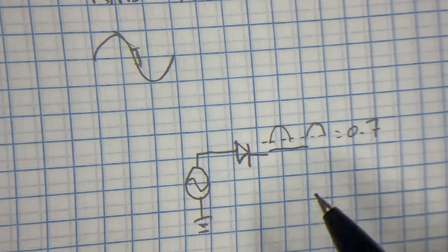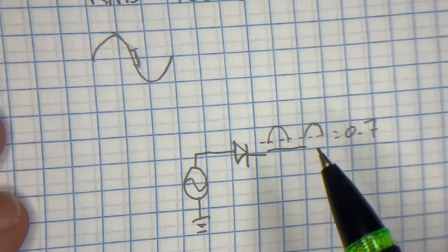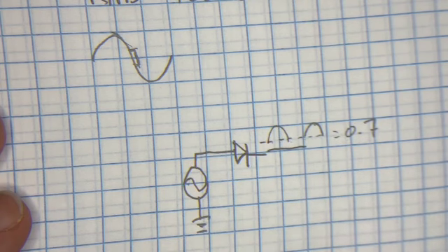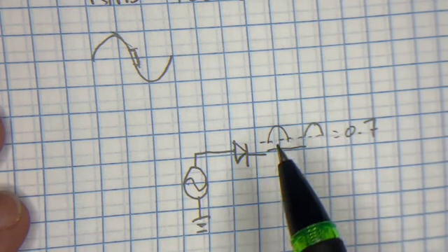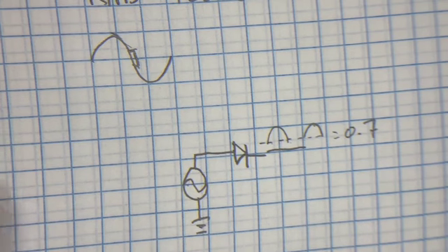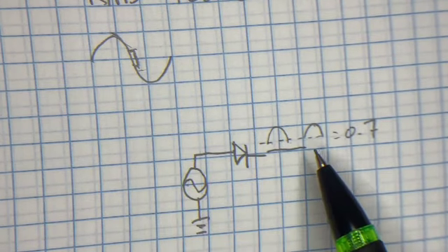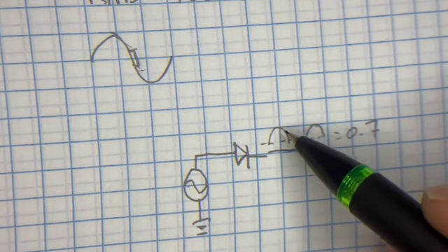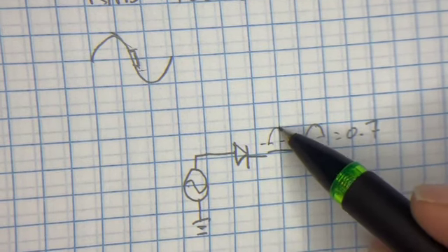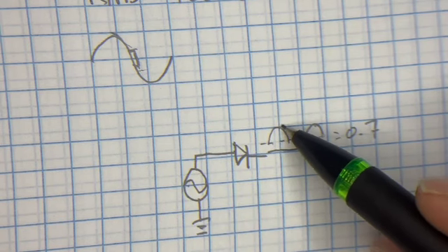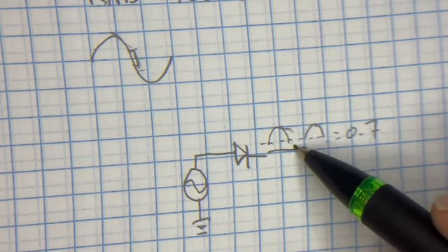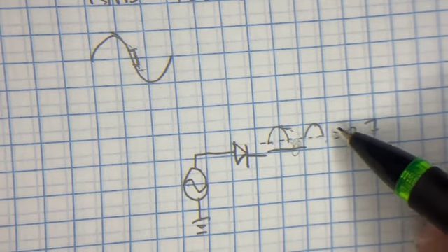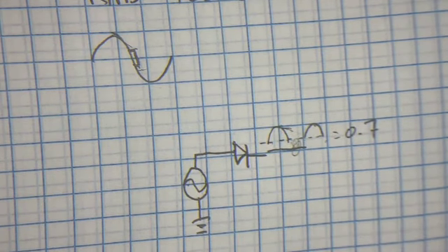And it's called rectified because it's no longer alternating current, even though it's got the humps. It's a direct current because it's always positive. That's the difference between AC and DC, right? An AC current goes positive and negative. DC is always positive. But this isn't very good either, because if something's requiring a particular voltage, during this time right here, it's off. So you get something that's kind of blinking.